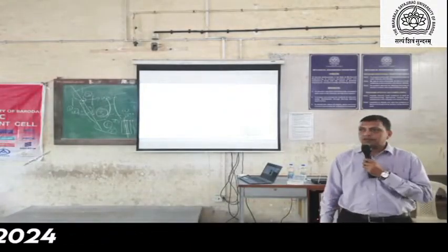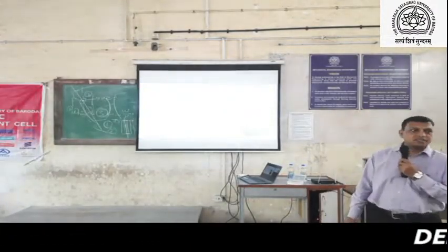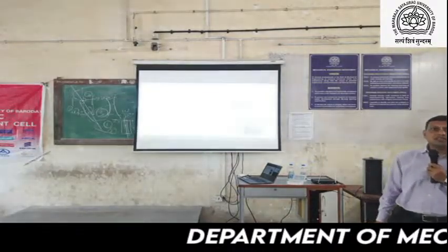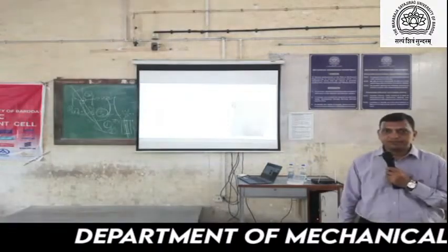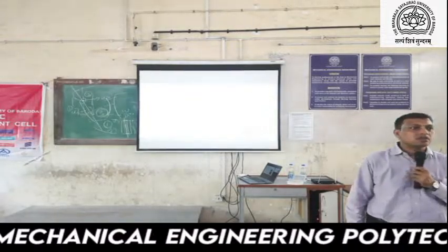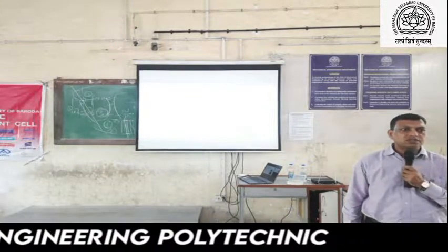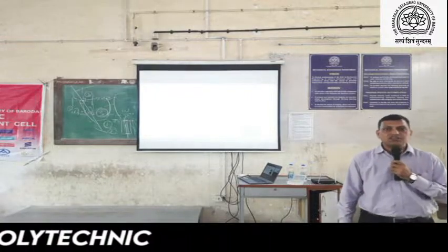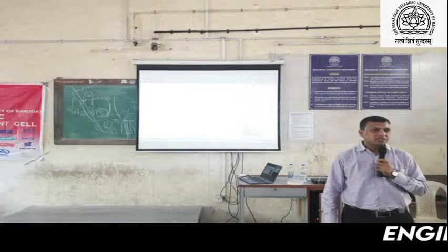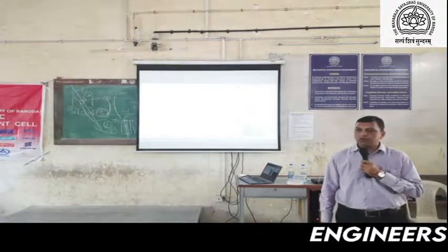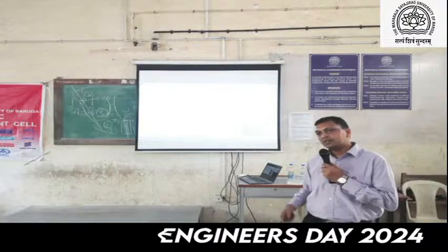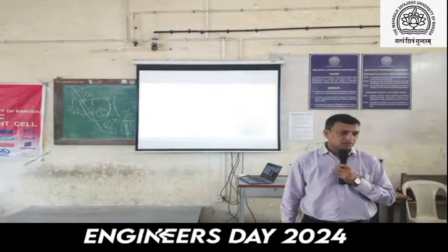After rough manufacturing, then we go for the hobbing. Hobbing is nothing but the tooth cutting of the gear. In this case, we require a particular cutter based on the size. The size can be defined based on the model. Any gearbox has a specific size based on that model. Based on the model, we can specify the capacity of the gearbox.